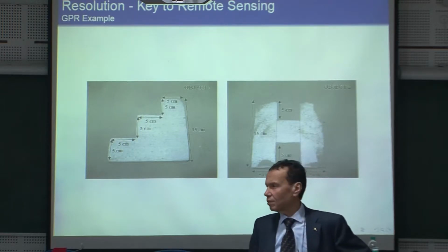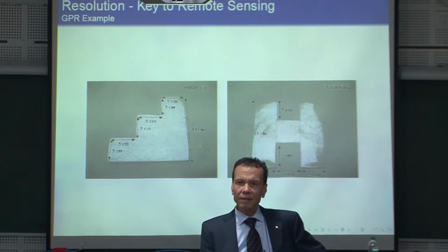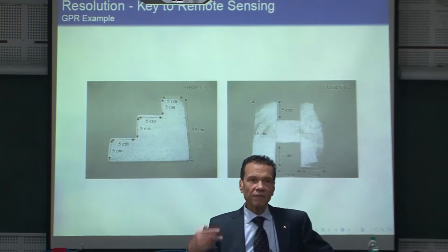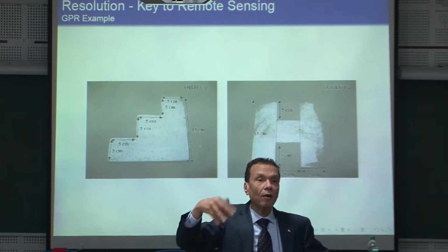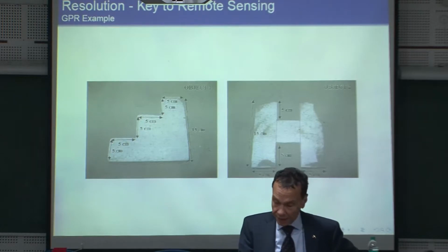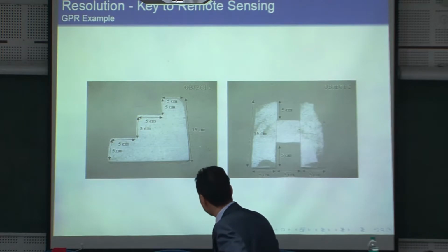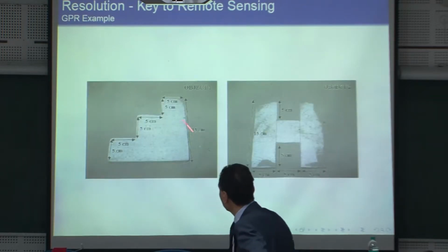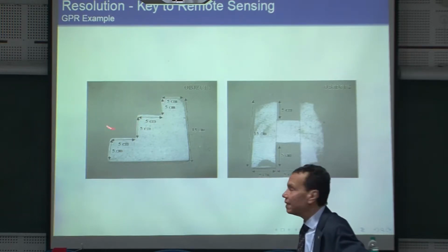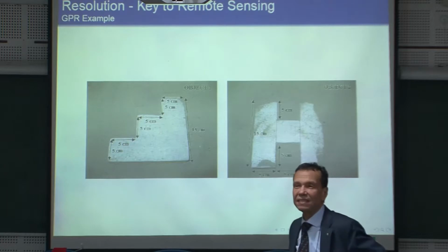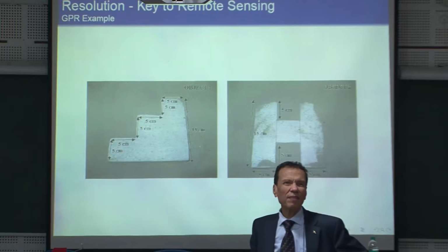So if you are an antenna expert, you know that there is what is called antenna cross-section, a radar cross-section. This is, if you have a target, how does this target look like? How big is it on the screen? This is the radar cross-section. And the idea of this F1 was to have the wings in this case, and you can prove that the scattering at the different edges here cancels each other, so that actually the whole object will reflect minimum.